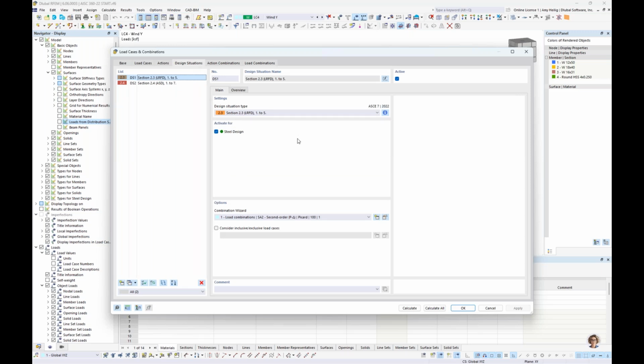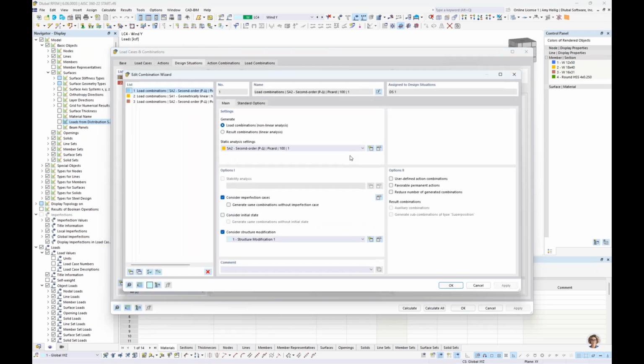We don't have time to go into much detail today, but if you refer back to a previously recorded webinar, AISC 360 2016 steel member design on our website and on our YouTube channel, I go through the requirements of Chapter C in much more detail. But for today, it should be known that under the combination wizard, if we take a look at this definition type here, that these load combinations will be run automatically according to a second order analysis. So we are considering both big P delta and little p delta automatically for the second order analysis.